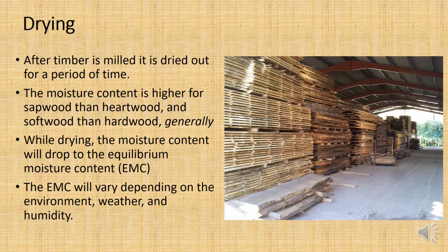Well, that's because there's water in the atmosphere, isn't there? It's what we call humidity, or rutuba in Arabic. And so as long as there is humidity in the atmosphere, there will always be some moisture inside the timber. And you need to reduce it to the minimum, which is called the equilibrium moisture content. And that is dependent on the humidity, the environment, the weather that the timber is being used in. So that's what drying looks like.